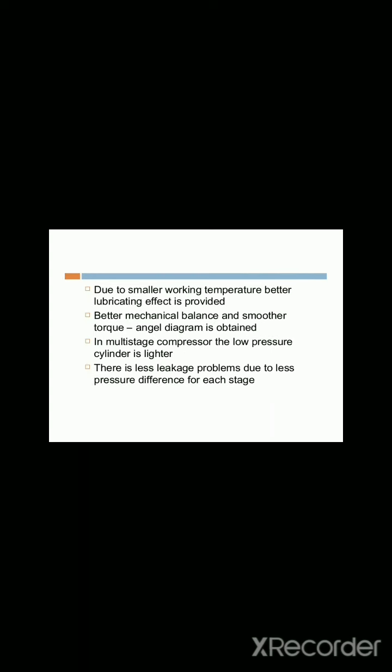Due to smaller working temperature, better lubricating effect is provided. Better mechanical balance and a smoother torque angle diagram are obtained. In a multi-stage compressor the low pressure cylinder is lighter. There are also fewer leakage problems due to less pressure difference for each stage.